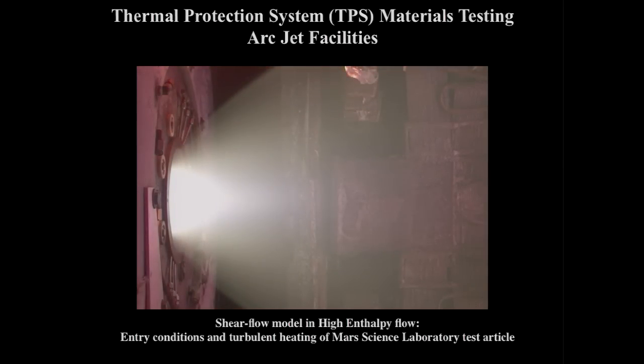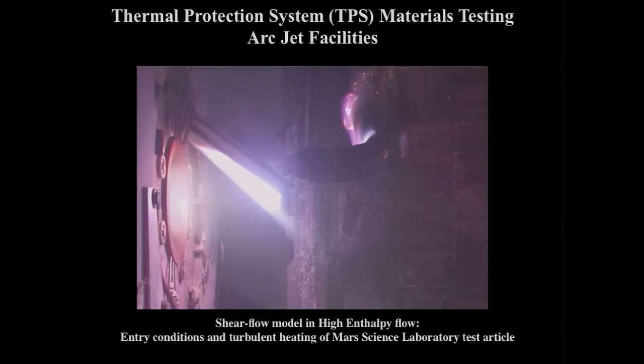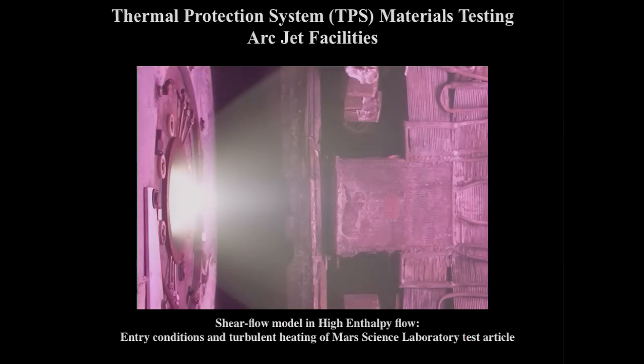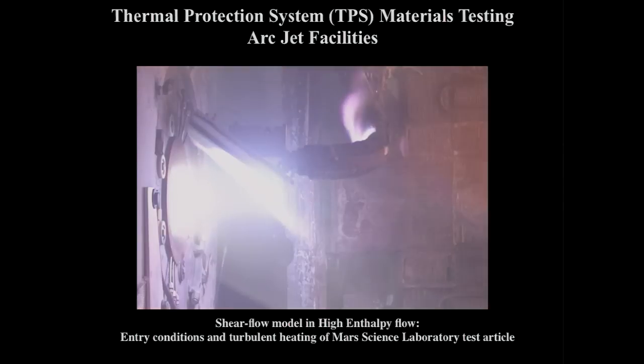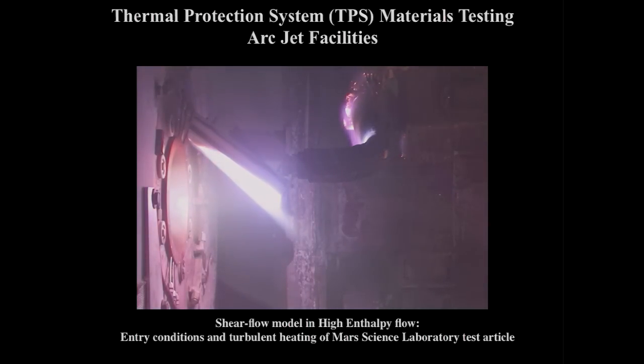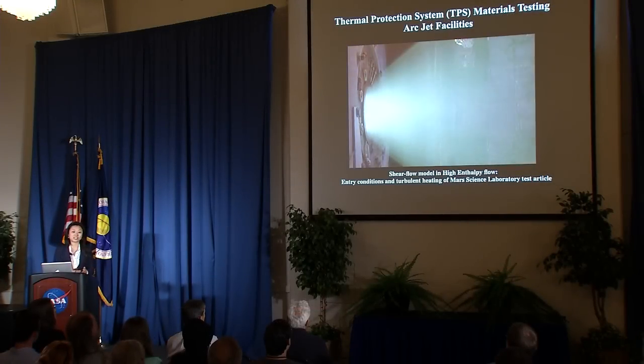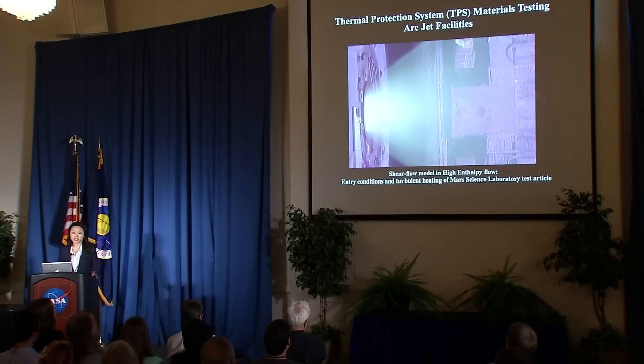Typically, for us to quantify how well it worked, we measure the heat shield material before, and once that's done, we measure the heat shield after, and that's how much material has ablated. The material has to ablate to dissipate the heat. In the fluid mechanics lab, we developed a better way to do this, to actually see what's going on between the beginning and the end.